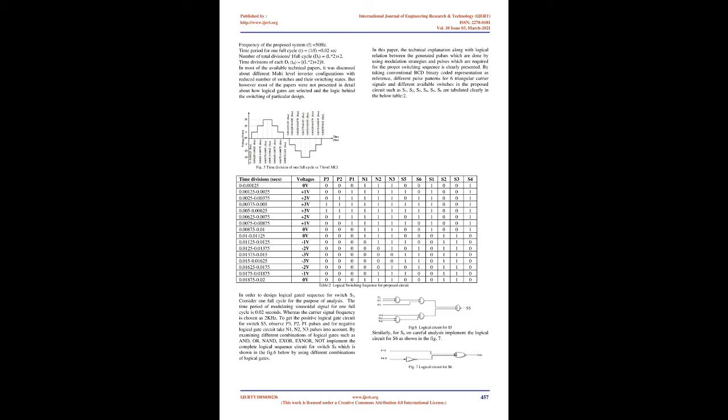To generate level shifting pulses, there are different techniques which are presented in various papers 8-9. After detailed study, 3 techniques such as phase disposition (PD), phase opposition disposition (POD), and alternate phase opposition disposition (APOD) are discussed in this paper. Phase disposition (PD) PWM technique has carriers in the same phase above and below the zero reference line, as